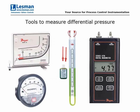So we look at the Magnehelic in the bottom left that's got a range of 0 to 1 inch of water column. Our Kinetizer LE burner has a gas pressure requirement of 40 inches water column. So of course, that particular Magnehelic gauge is probably not going to be the best for this application. It might be good for measuring pressure at low flow, but it's certainly not going to cover the high end that we need. So you'll want to know what the burner differential pressures are at high fire, so that'll help you dictate which method of pressure measurement you use.